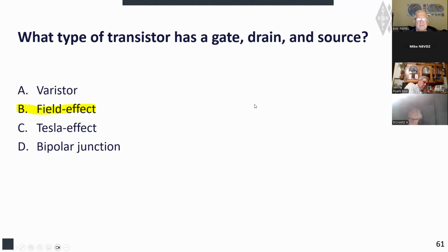Okay, gate, drain and source are the same as well. Gate is the base of a transistor. That's the terminal that gets the small signal or something that controls the flow of current between the drain and the source, or the emitter and collector. The source would be the same as an emitter, drain, same as a collector. But again, they just want an answer for that question, so you don't have to go into all the ins and outs of it.